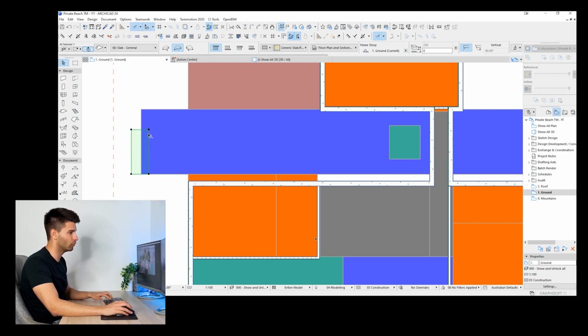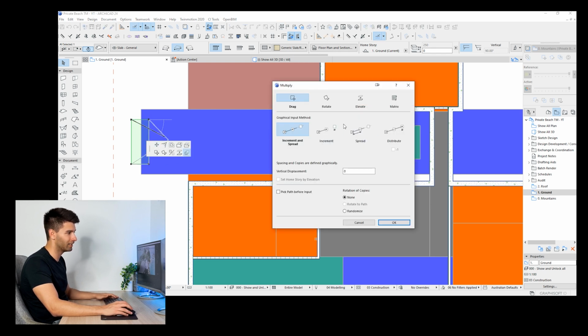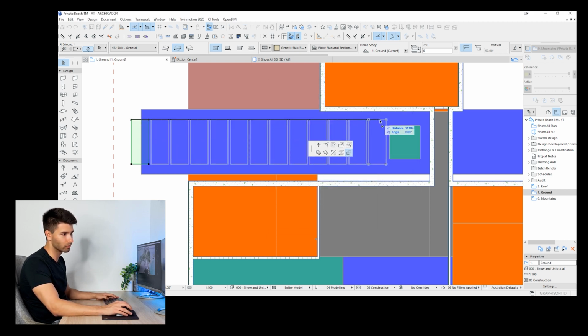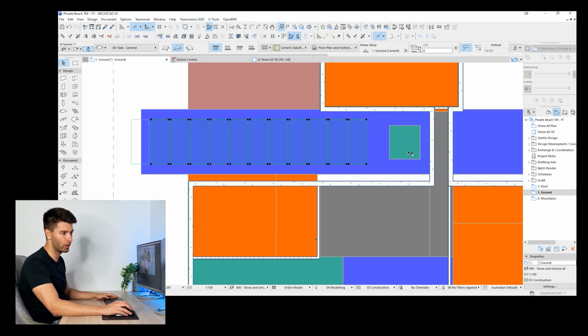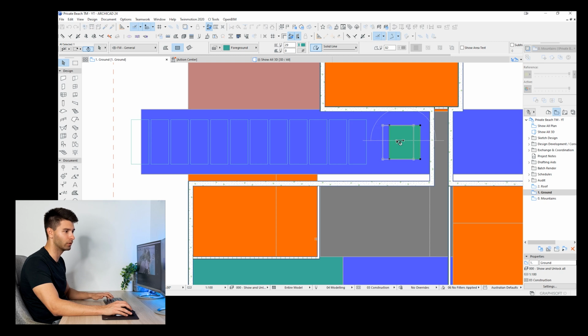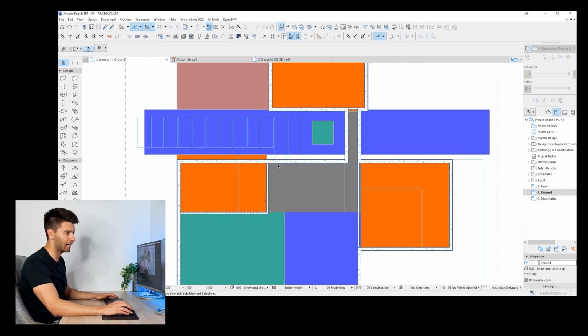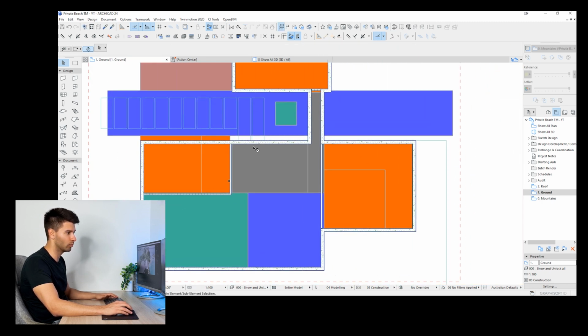The stepping stone for me will be somewhere in the center of this pool, which is 450 millimeters away, and we're going to have about a 100mm gap. So I'm going to quickly and easily space them 900 millimeters apart. So by pushing them across, we have 900 millimeters. I'm going to go one step back so we're not impinging on this landscaping that we're talking about previously, and then I'm just going to extend these last two slabs straight to the house, so the house actually has some sort of entryway, and this will be our door.